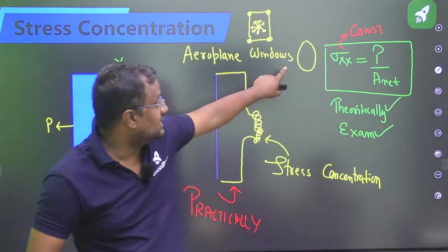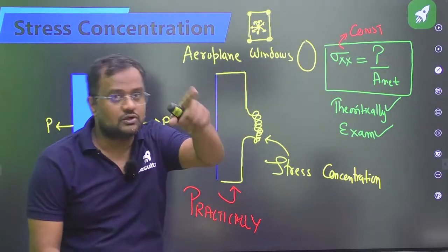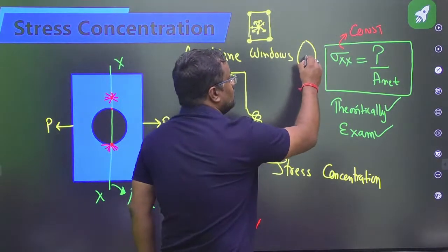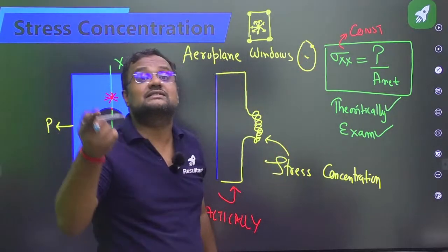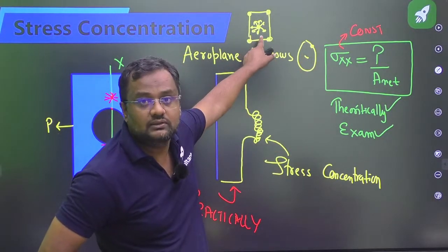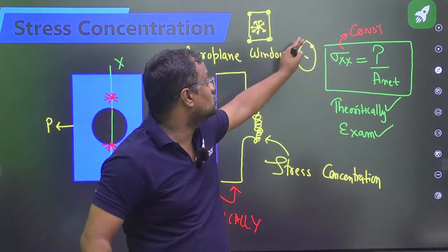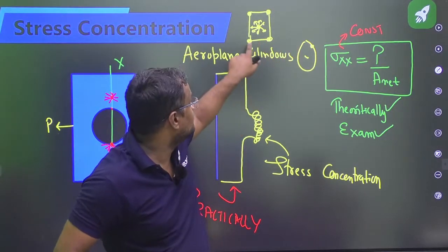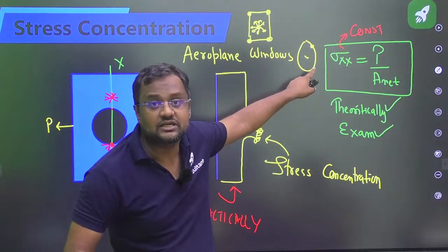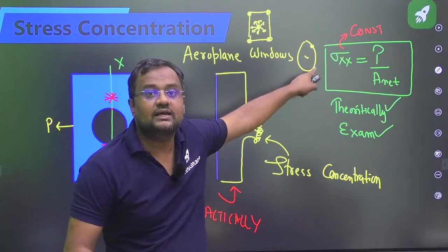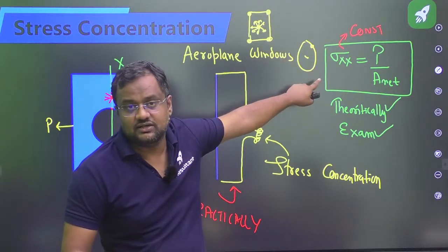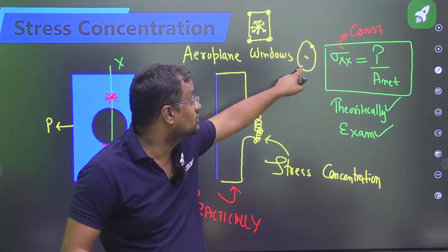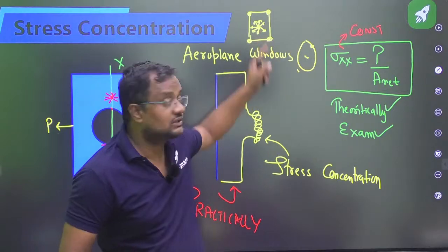So with an oval shape, guys, it is the same thing. This point can absorb the load in all directions, but not this. But discontinuity is less compared to rectangular. The curvature is not changing at any point, unlike here. It is smooth, a continuous curvature. So compared to this, there is less stress concentration. Therefore, nowadays all windows are like this, not like that.